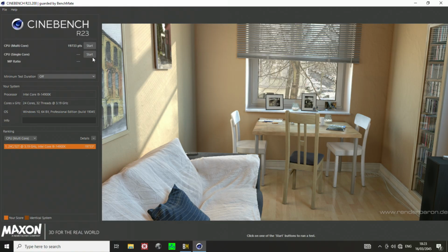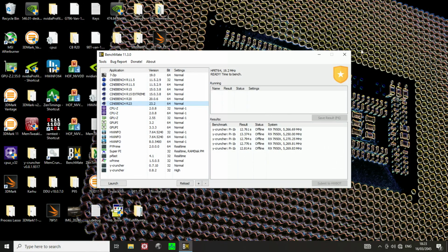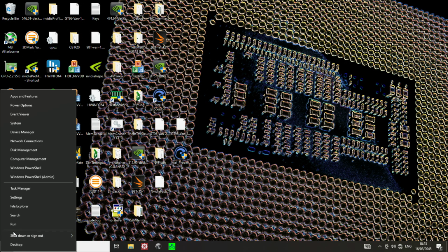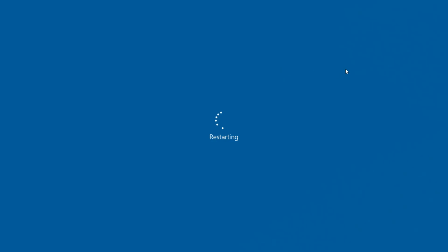Anyway, you can see that by adjusting the AC load line, I've made the performance drop even worse. This is just a disaster at this point from a performance perspective. So now let's take a look at how not to do that. Also, I would actually suggest that you do adjust the AC load line a bit, because if you're adjusting the AC load line, you would also want to adjust your VRM load line.